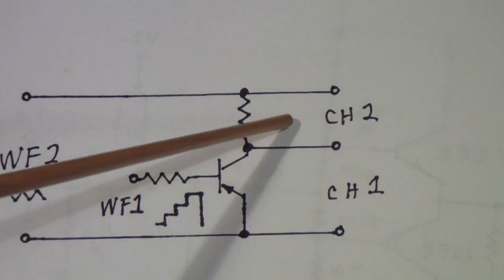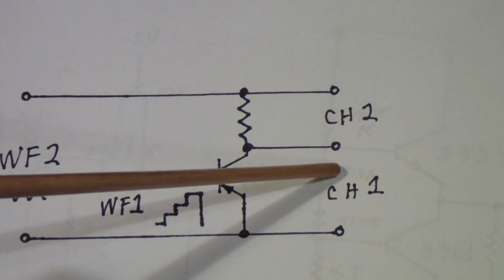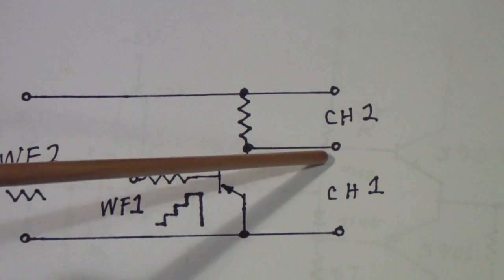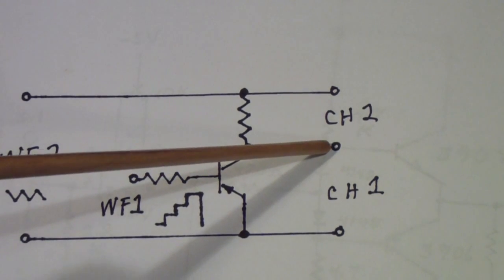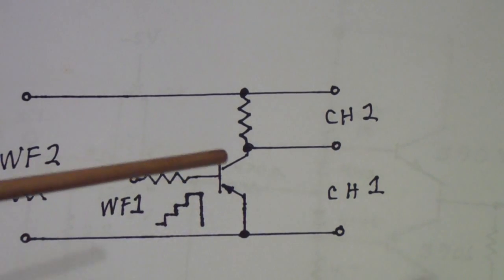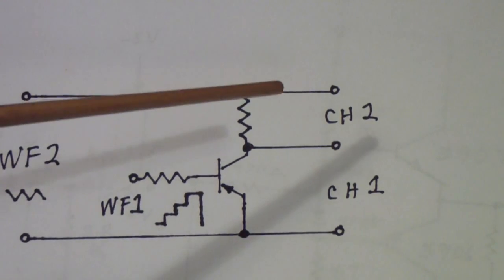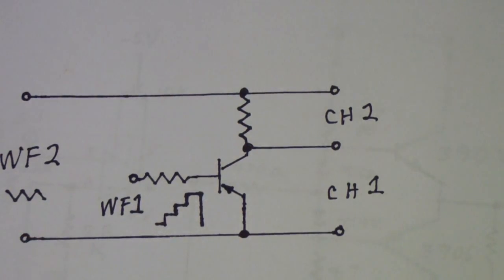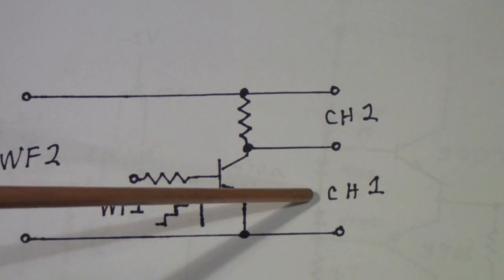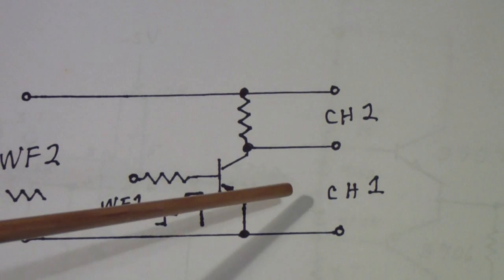The one other thing that I will mention about the Analog Discovery is, because it has differential inputs, unlike most of the octopus circuits that you see where this point has to be grounded, and then you have to invert one of the channels in your oscilloscope, in the Analog Discovery you can swap the plus and minus leads of the channel 2 and channel 1 scopes. They do not have to be referenced to a common ground. So this is one of the advantages of the way the Analog Discovery is designed, and it facilitates this kind of thing.